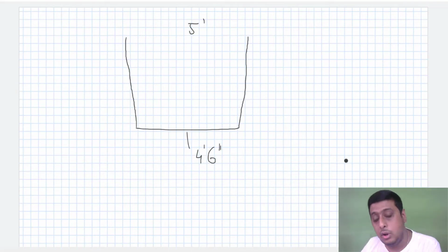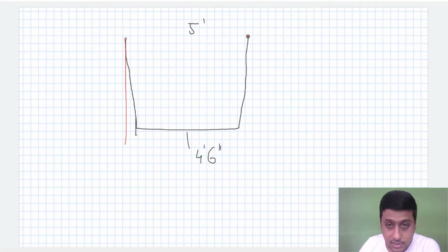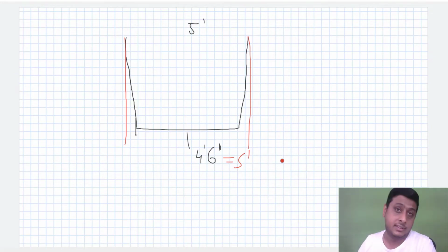So as a site engineer, you have to go and inspect the dimensions at the bottom and trim it off. You have to trim off this extra surface and make it exactly 5 feet, as given by the structural engineer. This is one of the major mistakes most site engineers make. Even I have done this. I learned it only in my later stages, because of which setting up my business took a lot of time. So these are the things a site engineer must observe.